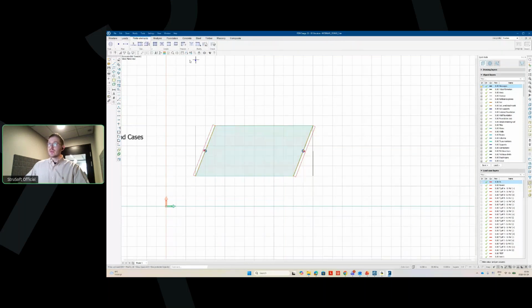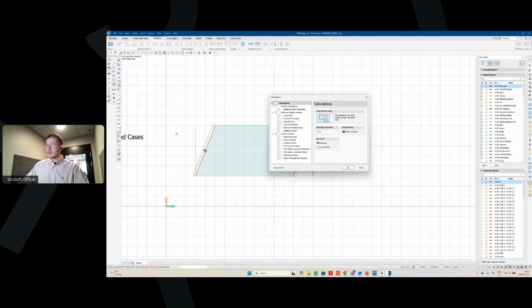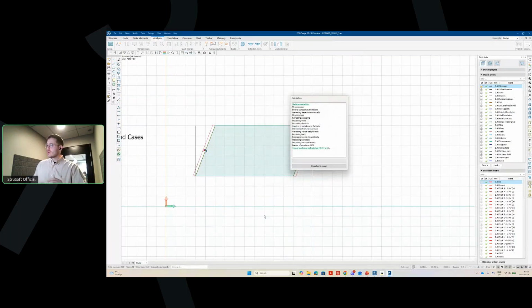Okay, let's mesh. No columns this time, so that seems fine. And now let's generate our load cases and the maximum of load group. Or actually, I can show you just the load cases, and then we can see how long time it takes to create the maximum of load groups. So hopefully this isn't too long.